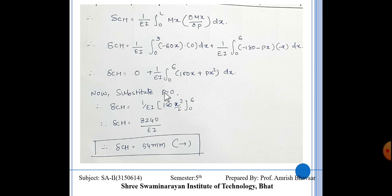Now put the value of P as 0 in this equation, so we will get delta CH equal to 1 upon EI, 180 x square by 2, integration 0 to 6. Putting the value of x as 6, we get 3240 upon EI in this case. After putting the value of EI, we will get the horizontal displacement at C, that is 54 mm towards the right.